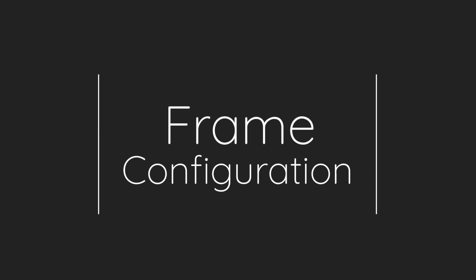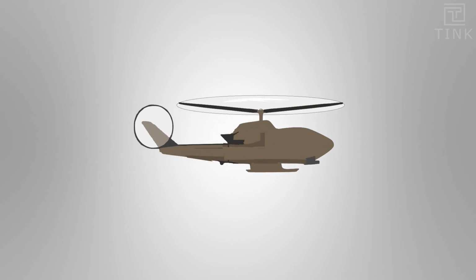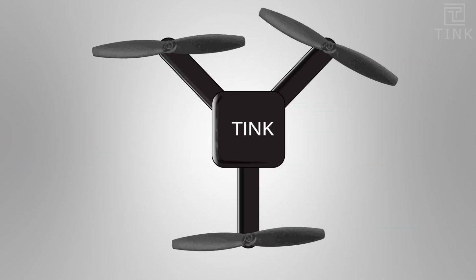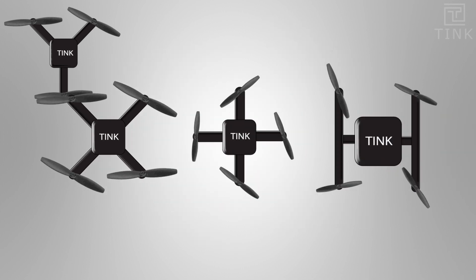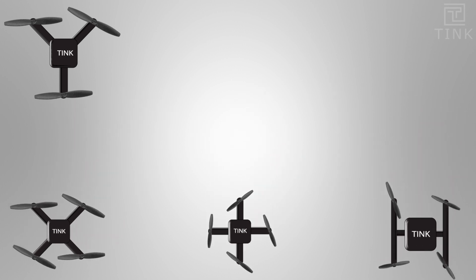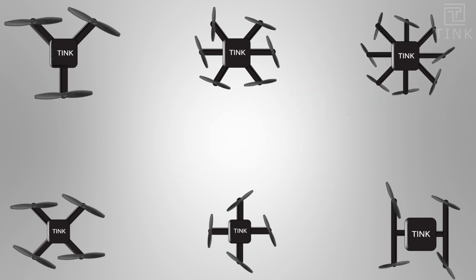The drones that are in the hobbyist market are available in many shapes and sizes. For example, the well-known helicopter drone, tricopter with 3 arms, quadcopter with 4 arms, and we have plus configuration, X configuration, H configuration within quadcopters, hexacopter with 6 arms, octocopter with 8 arms, and many more configurations. These configurations differ based on the purpose of your drone. For example, if you take aerial photography, then the H frame will be better to mount the cameras. Or if you perform stunts in the air, then the X configuration will suit the purpose. Since we are making a mild FPV drone, we will choose an X configuration.